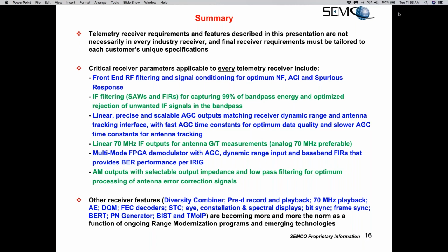Around 10 to 11 dB, you'll start seeing a little bit of degradation in the front end. What kind of degradation am I talking about? I'm talking about somewhere about 1/4 of a dB. So when you're looking for a receiver out there, you want to make sure that the noise figure of the receiver is somewhere between, say, 8 to 10 dB. And that will be just fine. You won't have any problems with that receiver if it's down in that area.